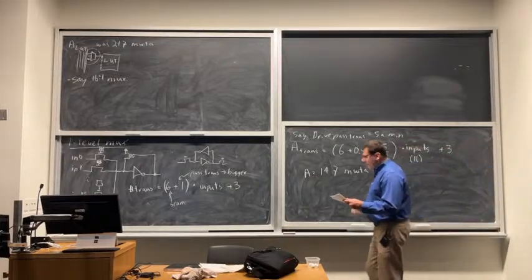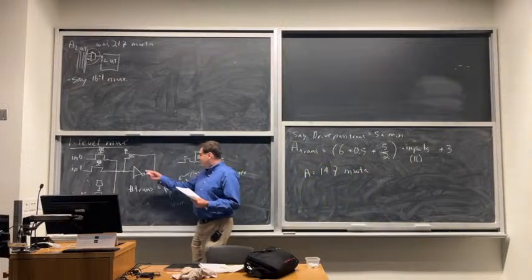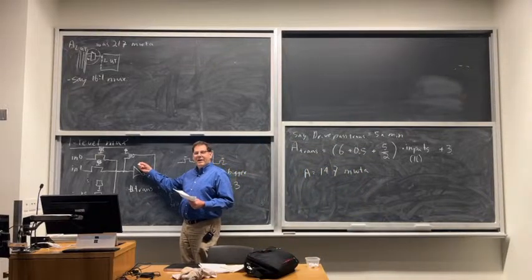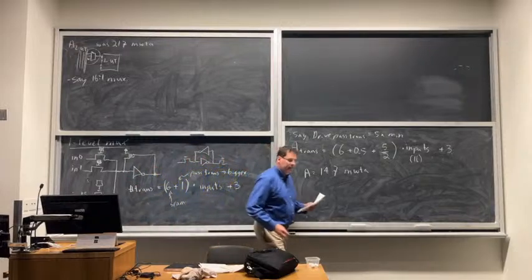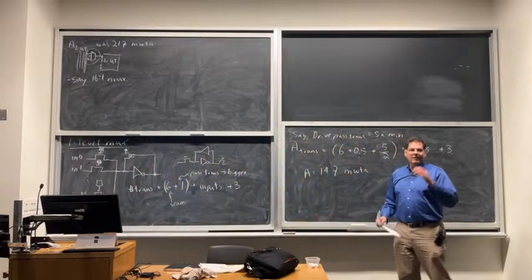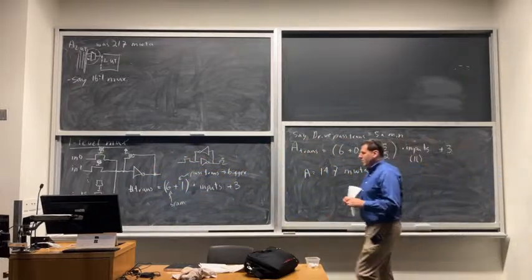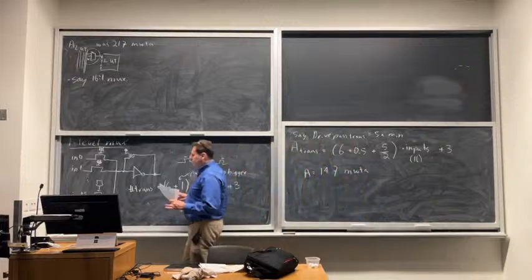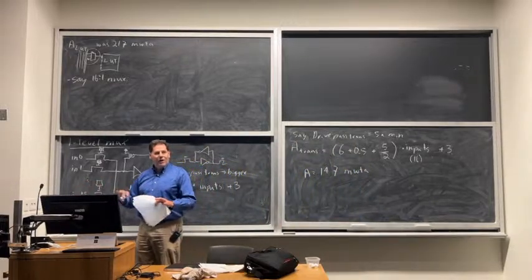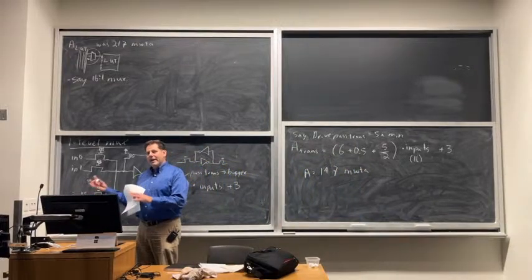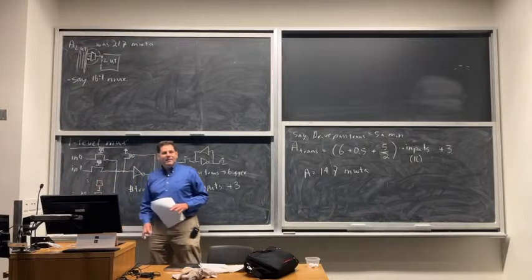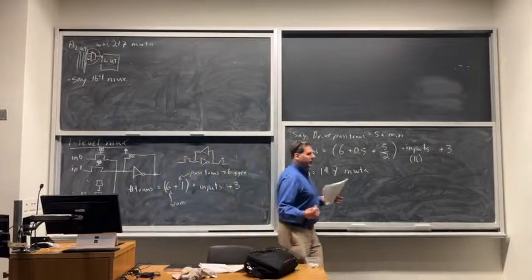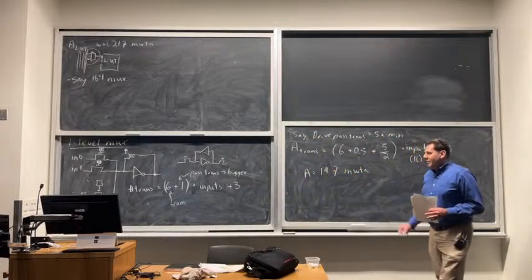Can I make this mux smaller? So clearly it's pretty large. Can I design this in a way where it takes less area? So you could say, well, cut the number of inputs. And I could do that, but it might impact my routability and have other knock-on effects. So if we're running CAD experiments, that would be a good thing to try. But I'm not going to do that. Just, can I change the way I build it to make it have the same functionality but take less area?